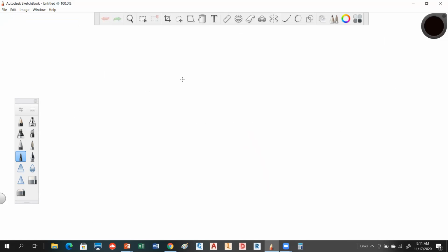If they tell you you have a joist that is a 2 by 12, let's say you have a wood joist that's a 2 by 12. You don't actually have 2 by 12. If you notice, your dressed lumber size is actually 1.5 by 11.25.